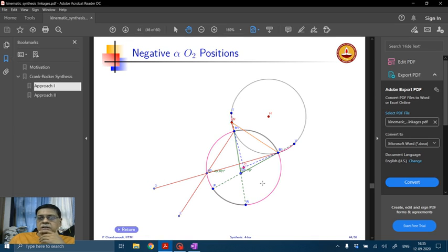This is the circle that we are seeing. So I've taken this point C and reflected it about B1 B1 dash. So you draw a perpendicular bisector, and this distance is the same as that distance. And then when you draw a circle, obviously it passes through B1 and B1 prime. Now, using the same logic, remember that the Grashof condition basically dictates that one cannot have the rocker crossing the line of fixed pivots. So the gray area is a lot larger for the negative one.